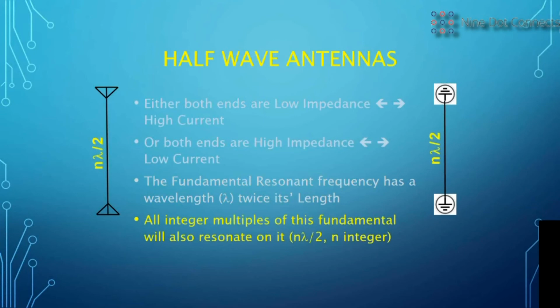If you go over to the right, you'll see a component that has a little bit of a spiral that's open on the end. This is an antenna that can be purchased. If you look down in the lower right-hand corner, you'll see a ground plane with a coax having its shield tied to it. The center point feeds the little quarter wave antenna part way up where the characteristic impedance matches.